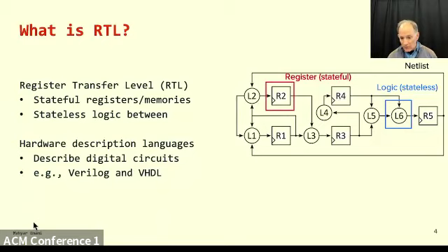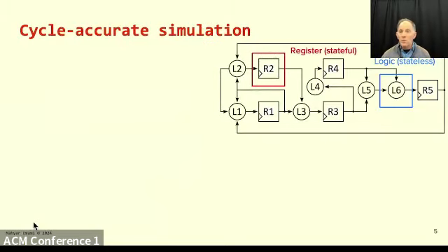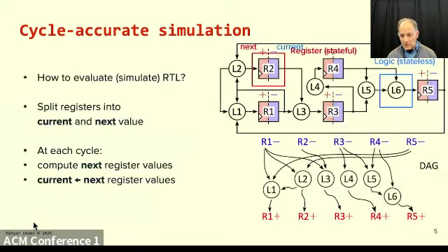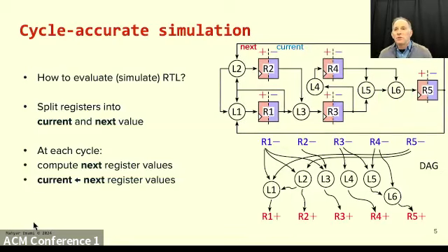And so we start from this. What we want to do is cycle-accurate simulation. We're not trying to do timing simulation, and we're not trying to do power simulation. We're trying to see the functionality of the circuit. So you start from a circuit like this, and what you do is split the registers into two: there's a current value and the next value.